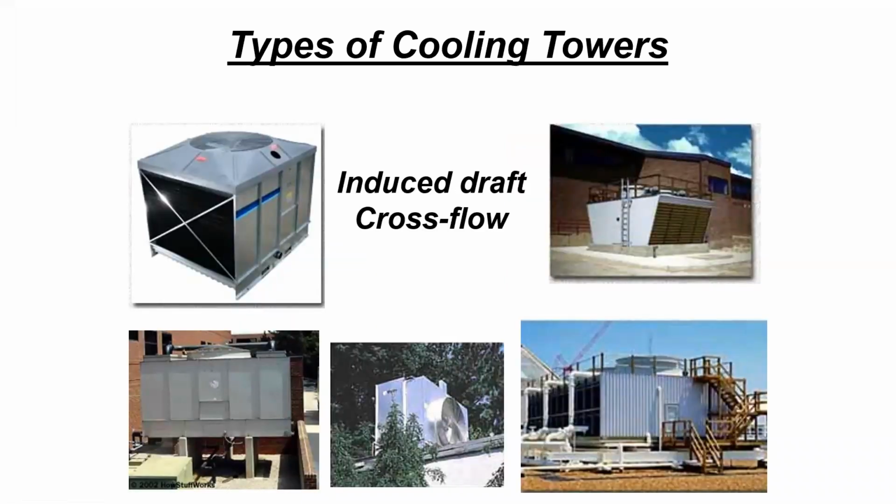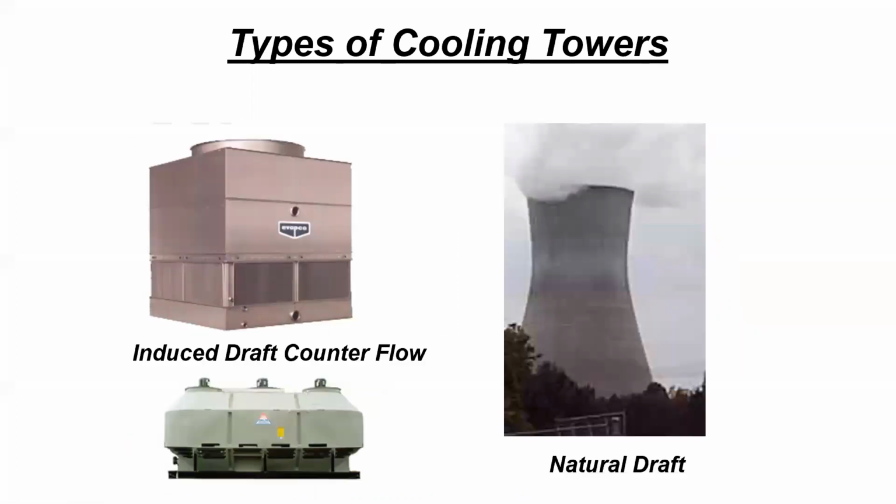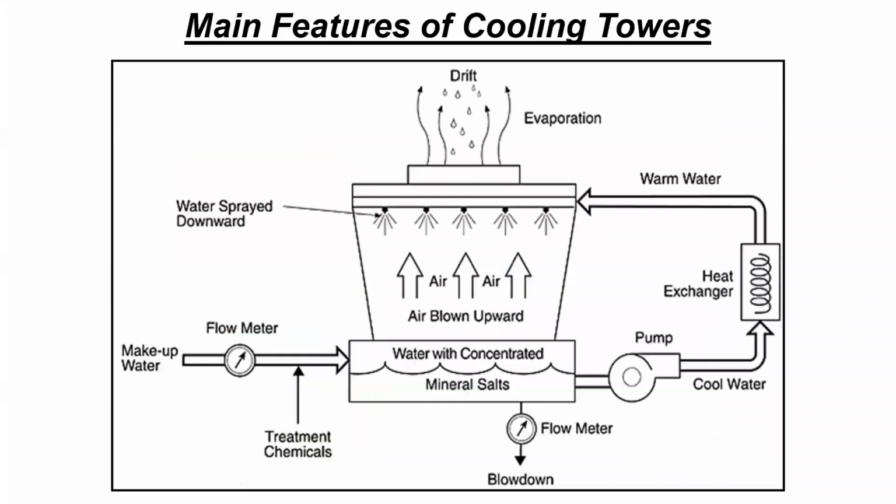In an induced draft cooling tower, on the other hand, you have the motor and fan on top of the tower, and you are pulling the air through the water, and it could be open from two sides mostly. It comes in different sizes and shapes: circular, rectangular, and square geometries. We also see natural draft cooling towers, where there's no fan involved in most cases, and the air is naturally induced going upward.